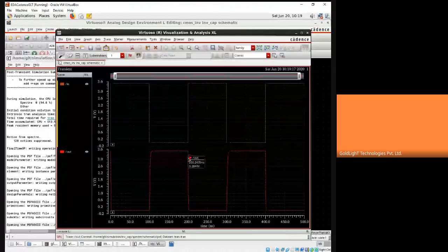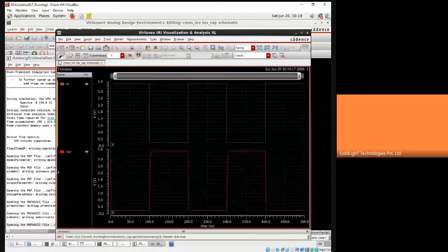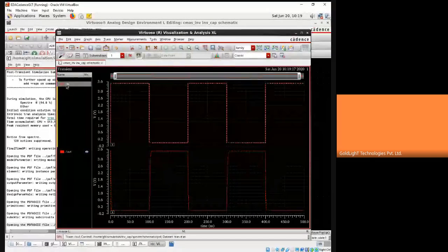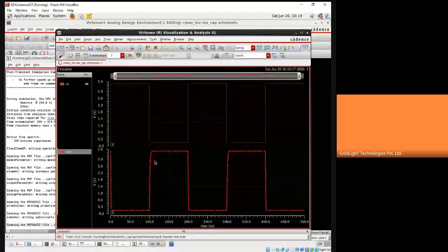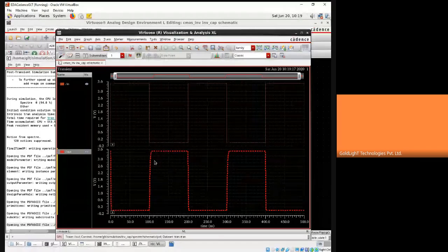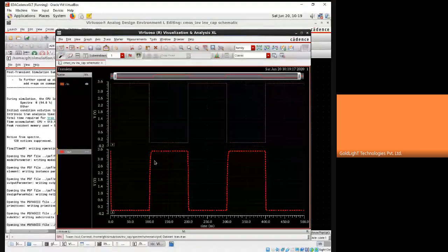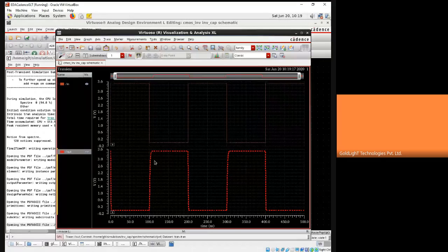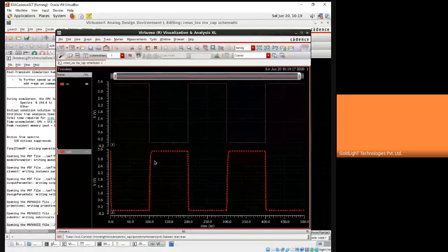See, this is the input and this is the output. Actually, this capacitor is used only if it is very necessary. That small peak won't destroy the entire system. For example, if you are going to design an ADC, it won't have that much effect. But in some designs, that might cause problems. In that situation, you are supposed to use a capacitor, and yes, that's filtering only.